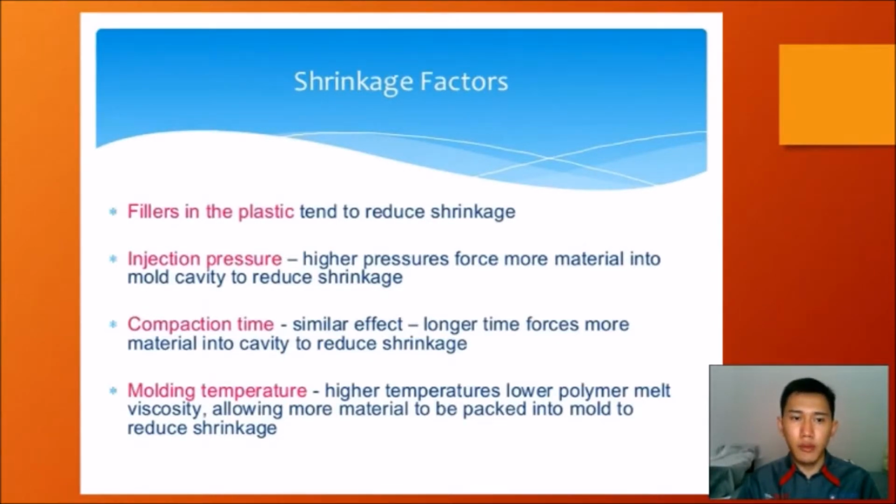Shrinkage. Shrinkage is the reduction in linear size during cooling from molding to room temperature. Polymers have high thermal expansion coefficients, so significant shrinkage occurs during solidification and cooling in the mold. The typical shrinkage values for polymers are as below.